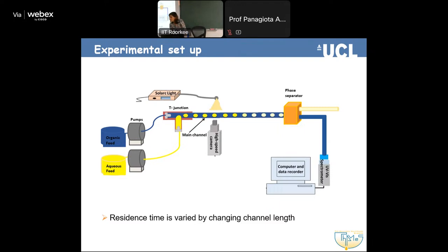How are we using ABS for separation, extraction? In the ABS, in all these cases, the aqueous feed or one of the ABS phases will have the metal, and the other phase will have the extractant. When we put them together, the metal will go from the aqueous phase to the organic phase.